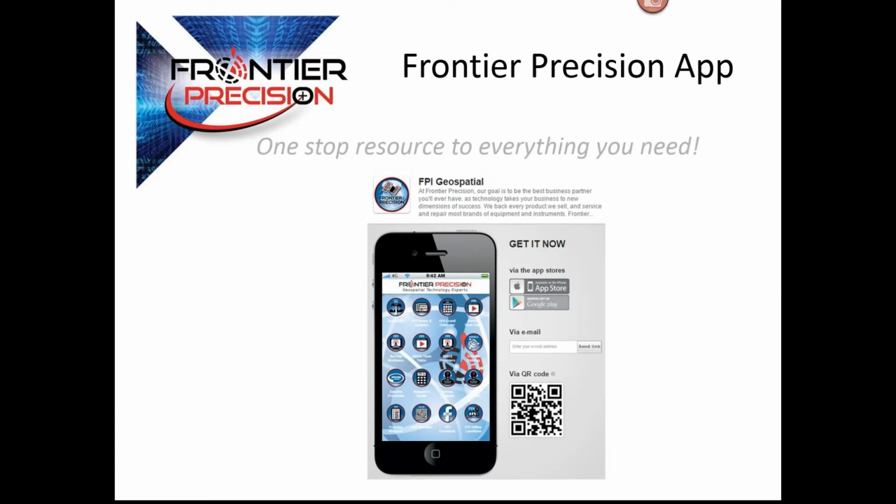Another question: are vertical accuracies better with VRS as opposed to setting up your own base station? So it goes back to the site calibration that we discussed in the webinar today. That's all relative to the site calibration. Like I said, when you just log into the VRS and get a vertical, it's all relative to the VRS elevation and your geoid model. So if you're checking into a benchmark that has no relation whatsoever to the VRS, then your vertical is not going to match.